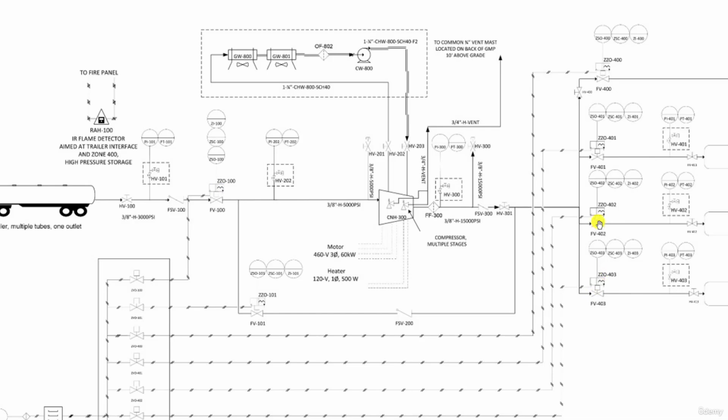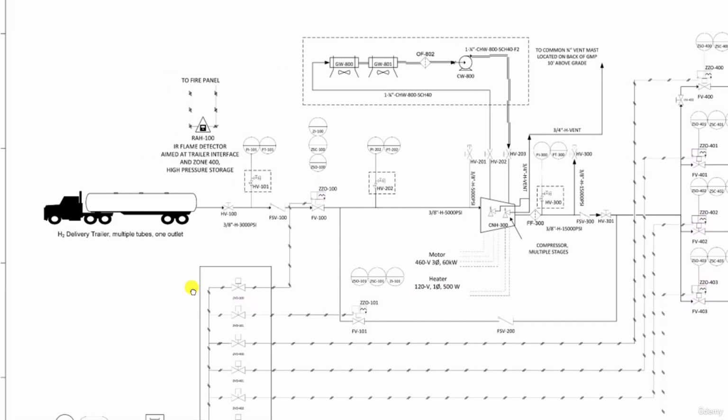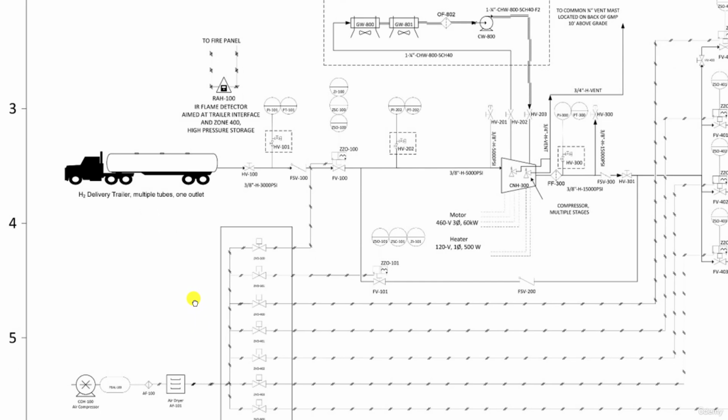As soon as the instrument air supply is cut off, the process valves will be closed by the action of the springs. So imagine the plant is operating under normal condition, one trailer is connected and hydrogen delivery is in progress. Then, all of a sudden, an operator detects a hydrogen leak, let's say somewhere here. An emergency response to this is to shut down the air compressor. This will stop the instrument air supply to all of the actuators, which will immediately close all the process valves, therefore providing containment of the hydrogen trailer and preventing any further hydrogen leak and its associated hazards.